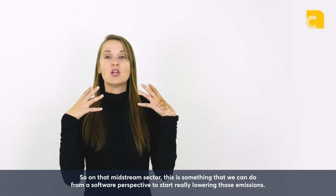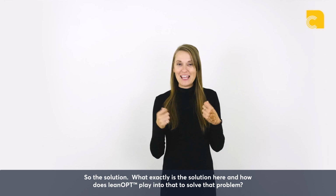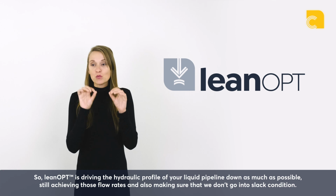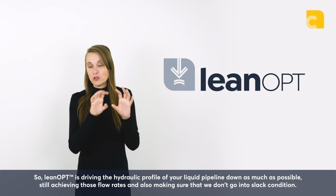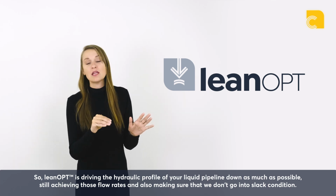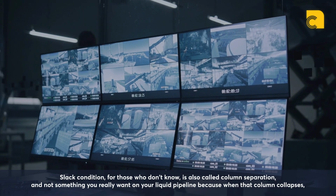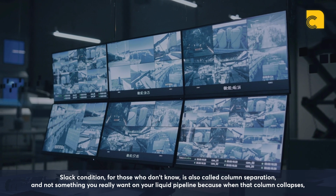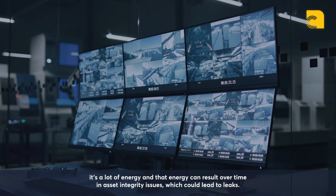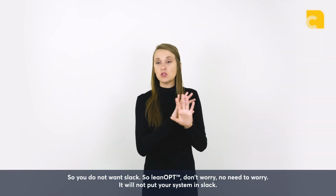So the solution, what exactly is the solution here and how does leanOPT play into that to solve that problem? So leanOPT is driving the hydraulic profile of your liquid pipeline down as much as possible, still achieving those flow rates, and also making sure that we don't go into slack condition. Slack condition, for those who don't know, is also called column separation, and not something you really want on your liquid pipeline, because when that column collapses, it's a lot of energy, and that energy can result over time in asset integrity issues, which could lead to leaks. So you do not want slack.